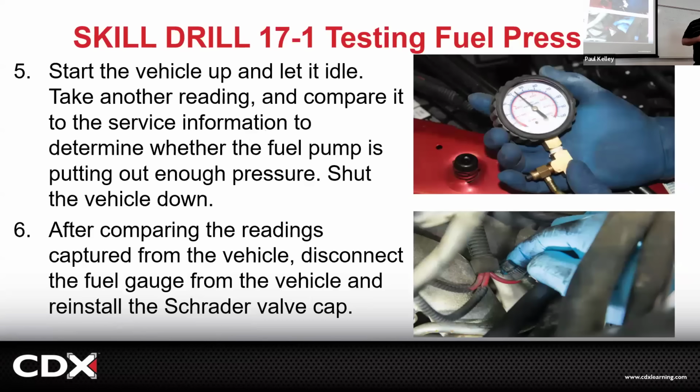So another thing that we'll do that's not part of this is I'll measure the fuel pressure. And sometimes what I'll do is I'll get a little can or a water bottle, a Gatorade bottle, and I'll squeeze this little button right there. You guys can see that button. That's going to relieve your fuel pressure. I'll squeeze that and that'll really tell me how much it's flowing.